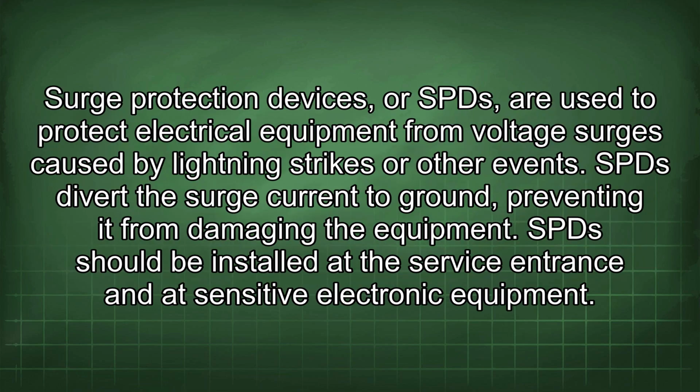Surge protection devices, or SPDs, are used to protect electrical equipment from voltage surges caused by lightning strikes or other events. SPDs divert the surge current to ground, preventing it from damaging the equipment. SPDs should be installed at the service entrance and at sensitive electronic equipment.